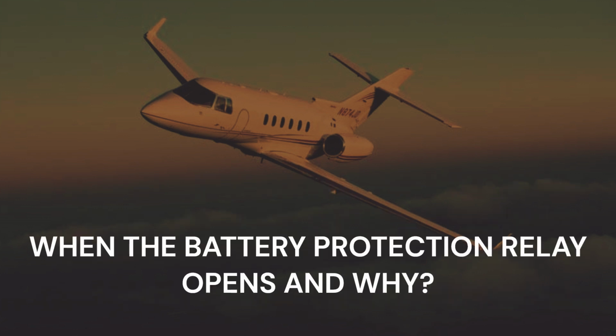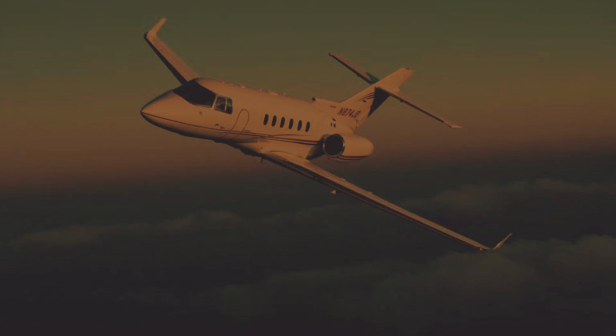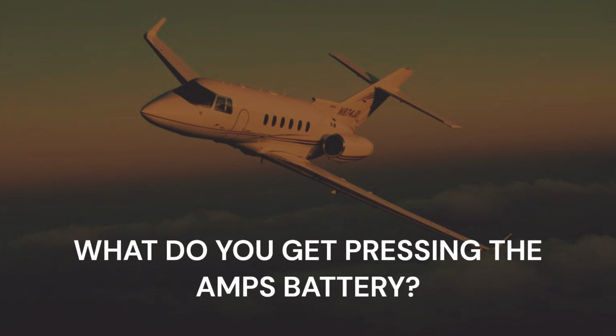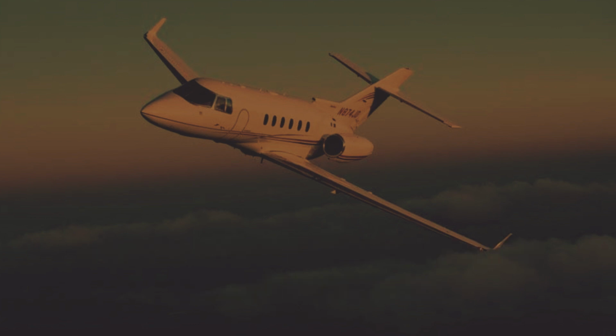When does the battery protection relay open and why? If the external power voltage drops below 24.5 plus or minus 0.5 volts or exceeds 29.5 plus or minus 0.5 volts, in order to remove power from the battery contactors. What do you get pressing the amps battery? The battery charging rate will be displayed.